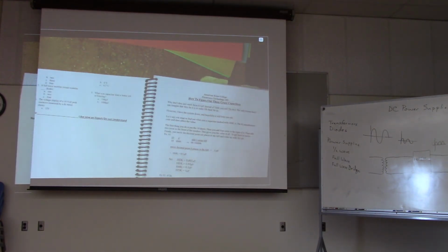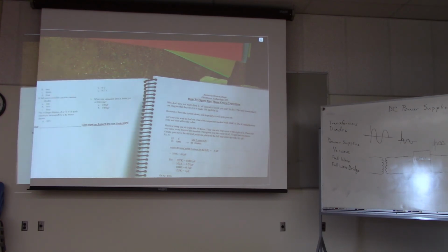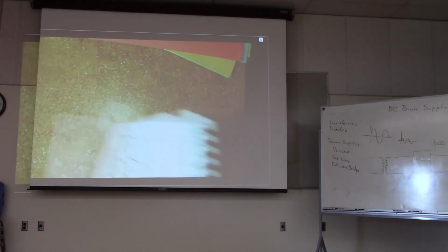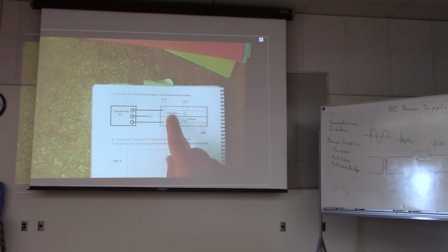So, any questions about the lab? Yeah. Just to make sure I understand, so building the circuit, that component is labeled 1N4001? Yeah, that's the diode. Okay. So that's this guy up here. Remember, the diodes are labeled with a stripe on one side. That side corresponds to the cathode. So this little marker here represents the stripe on the diode.